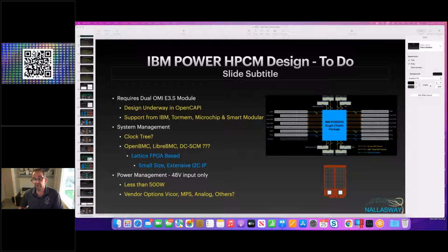So the way I'm envisaging it right now, you've got the 16 lane one here. These are the 32 lanes of PCI off of the Power 10. So you've got 16 going to one slot, and the idea there would be you'd plug in a NIC 3.0 here, which would have a Mellanox card or whatever, giving you network traffic out to the outside world.